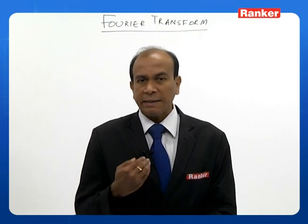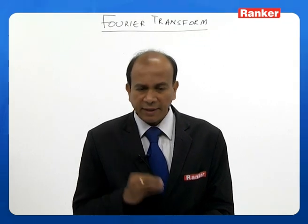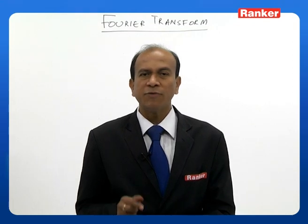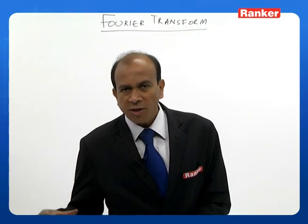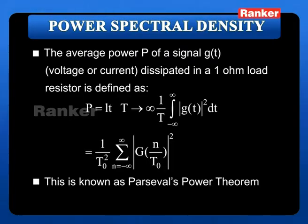So when I talk in terms of the frequency domain, this can be written as 1 by T naught square summation n equal to minus infinity to plus infinity mod of g of n by T naught whole square. So when I sum all these components, I will get the average power of the signal. So this is called Parseval's power theorem.